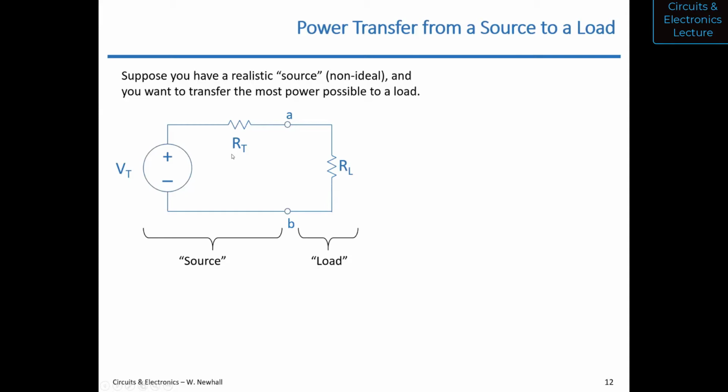I mentioned that on the back of your stereo, it might say something like 8 ohms next to a speaker output. That 8 ohms is actually the Thevenin resistance of that output. There's a big complex circuit in there with an amplifier, transistors, capacitors, but at audio frequencies, you could model that amplifier with the Thévenin-Equivalent. We're going to call that a source. It's not an ideal source. On the right side, what you connect is the load, which would be the speaker in the amplifier case.